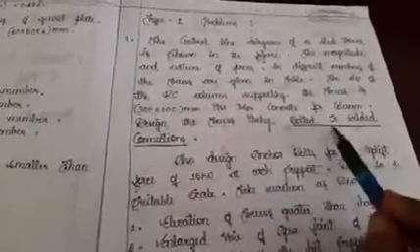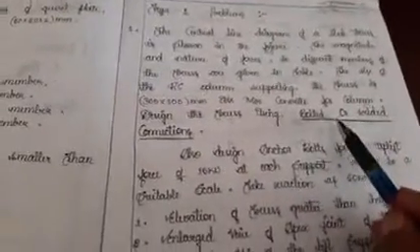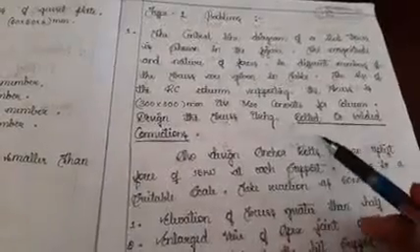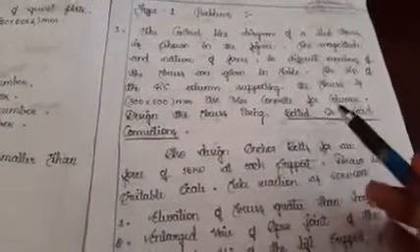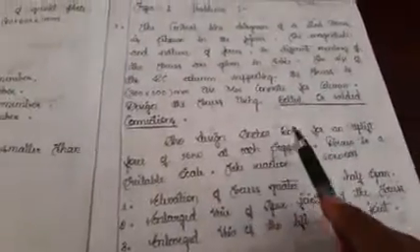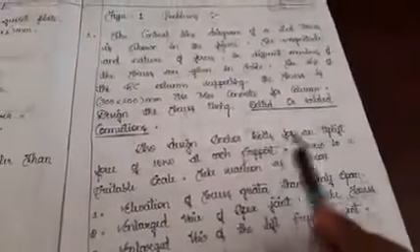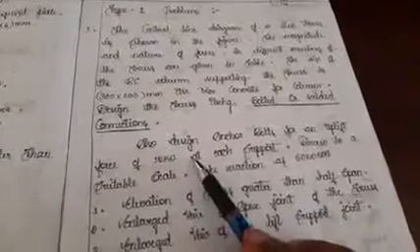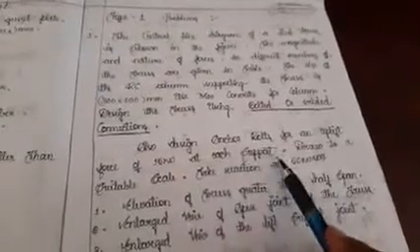This connection is left to you, it is up to you; you can choose either a bolted connection or a welded connection. And also design anchor bolts for an uplift force of 15 kilonewton at each support.